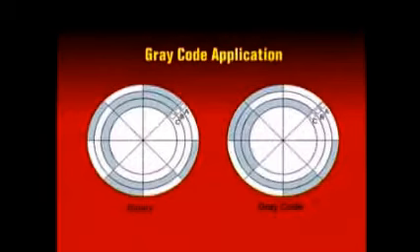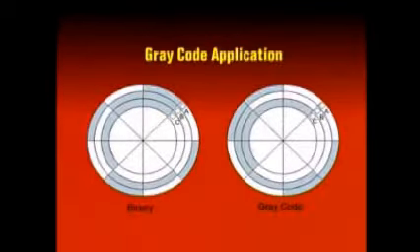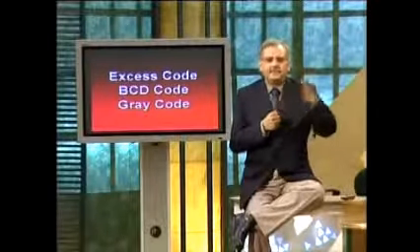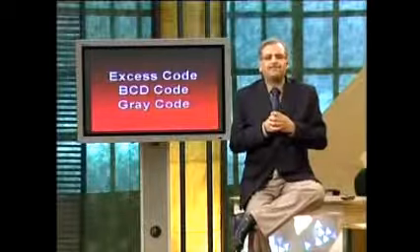The conducting and non-conducting strips follow a gray code pattern 000, 001, 011, 010, 110, 111, 101 and 100, representing decimal numbers 0 to 7. Now, even if the brushes are misaligned, the LEDs would always display the correct count value. We have just looked at an example of the gray code. We might be looking at other examples of gray code during the course of the study.